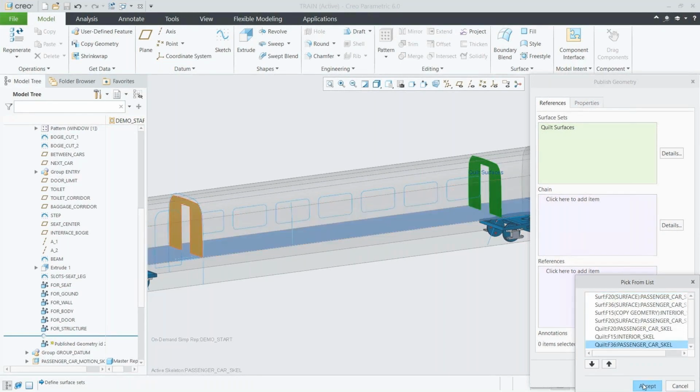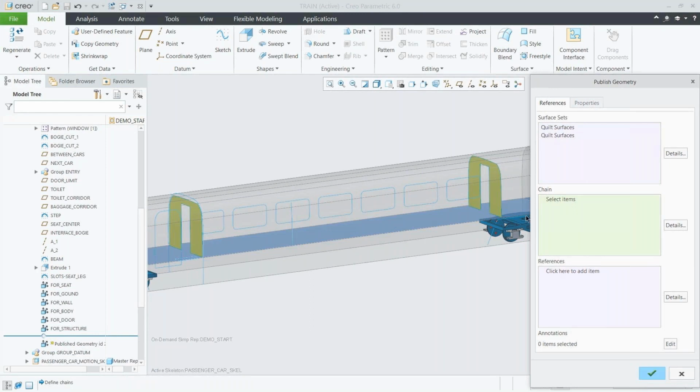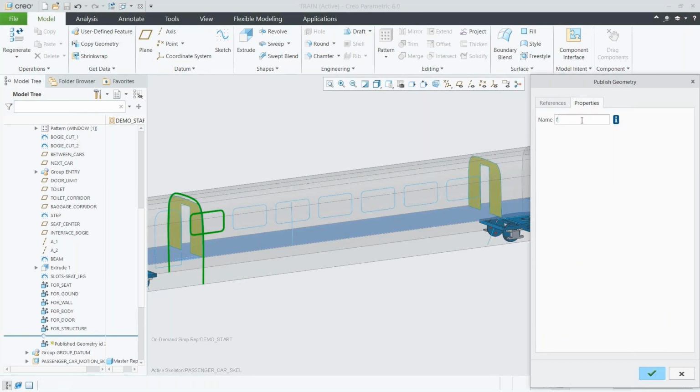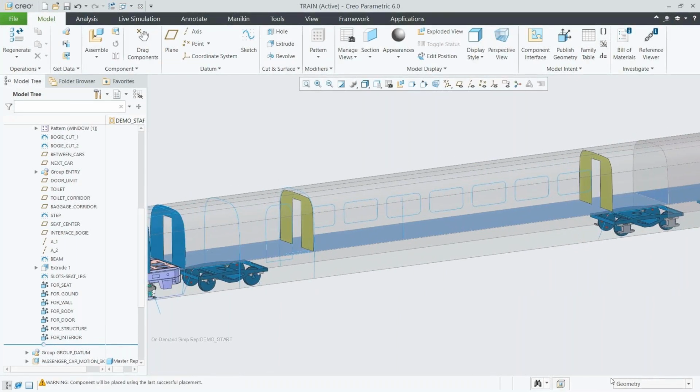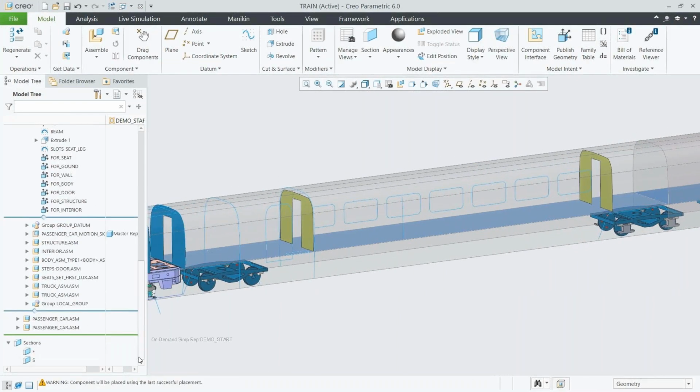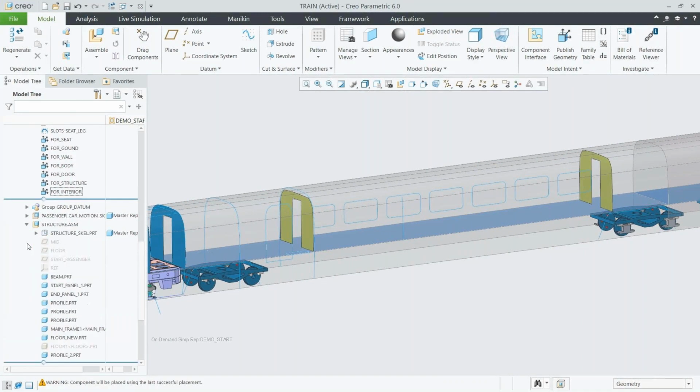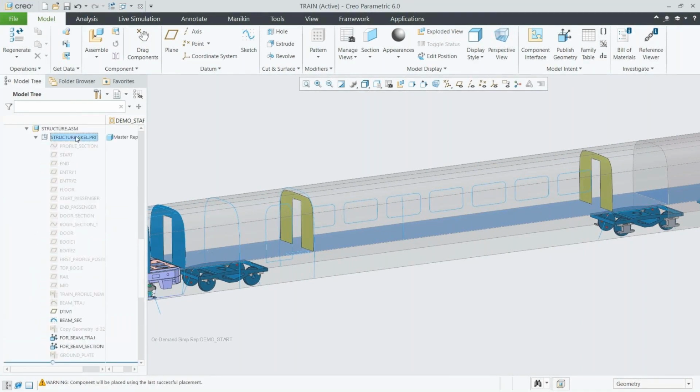We're actually able to take it from whatever assembly or part that this is in and copy it into another part or assembly wherever we want. So we're grouping these together so that we can take it somewhere else. I don't want to have this whole top level assembly open to do my particular work. So you can just have these particular pieces moved into the subassembly you're working in or the part.